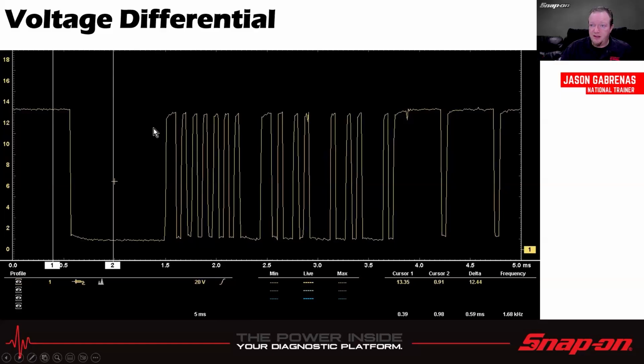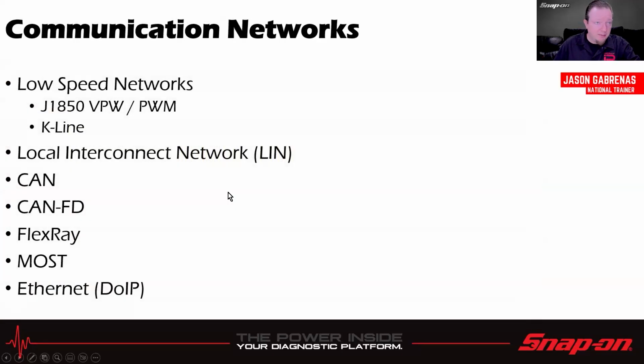So if I needed a 12-volt threshold and I had this, above 12 volts, then we're good. If I had a 12-volt threshold and I was getting 10 volts on a pulse, then the computer might not even recognize that as valid data. It'd be weak data. It wouldn't be crossing that threshold to be valid as a 1. So it depends on the computer system once again. But if you have a weak signal, that might be your communication problem right there. And we'll take a look at a couple examples a little bit later.